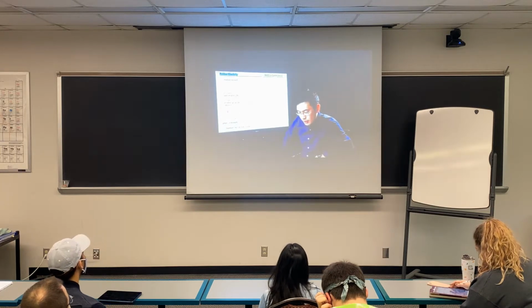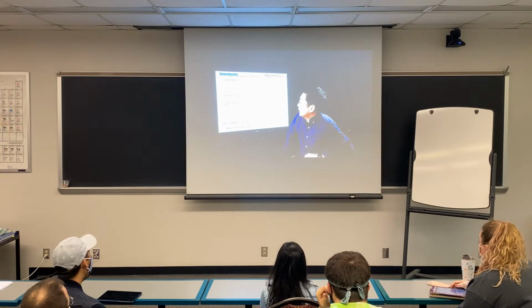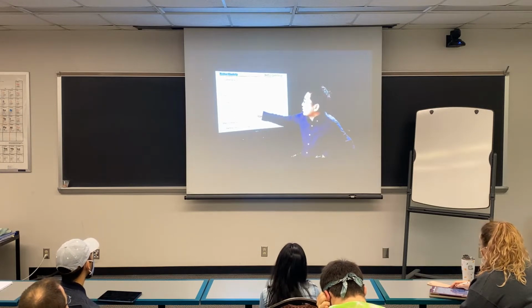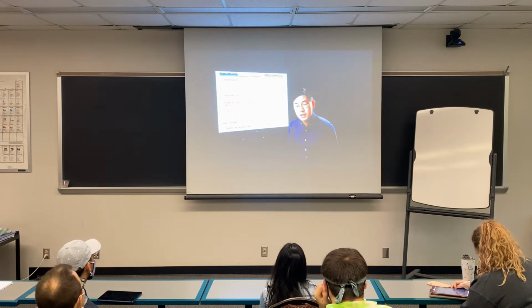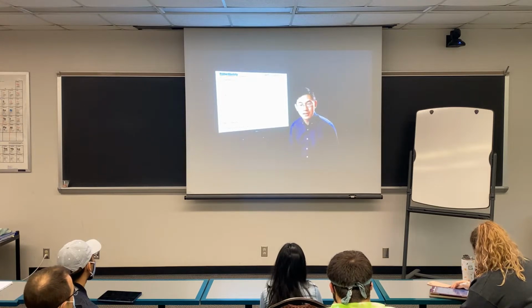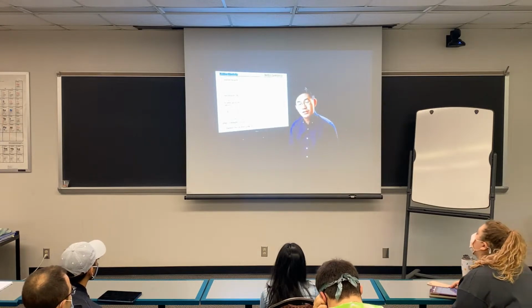And the other one is affine deformation. Affine deformation discusses how the network will deform affinely to the macroscopic deformation. This introduces an idea of a phantom network to lower the effective number of crosslinks. Phantom network, what does phantom mean? Phantom means something is not real, something is idealized, like Phantom of the Opera, something ghost-like.